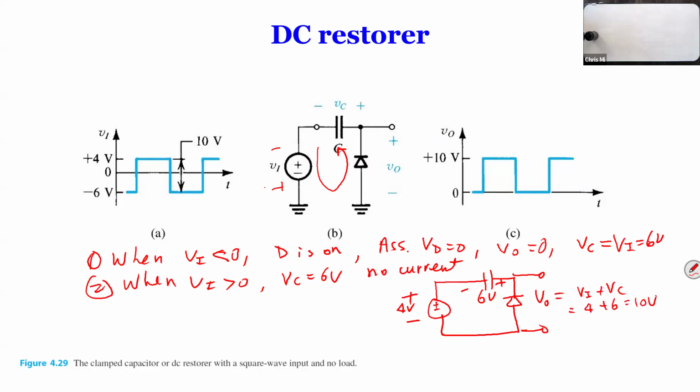So what we're saying is that if the capacitor size is right, and because there's no resistor in the circuit, ideally the voltage on the C won't change instantaneously, but it's okay. For this example, we're just assuming that the voltage on the capacitor would change to 6 volts initially, but it would take some time, because the diode actually has some internal resistance, right? You remember the SPICE model, right?